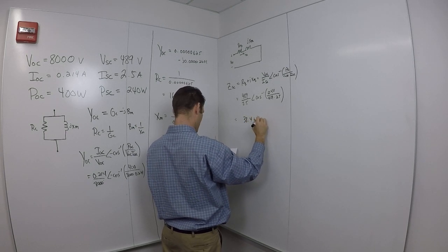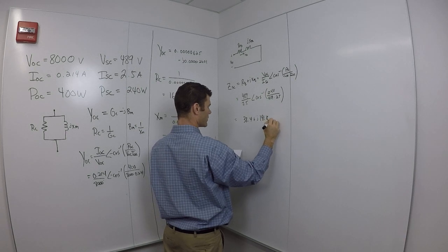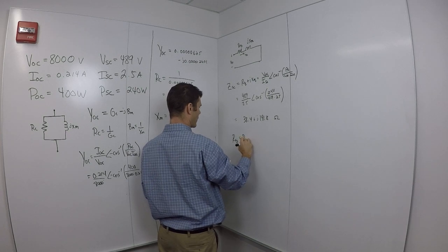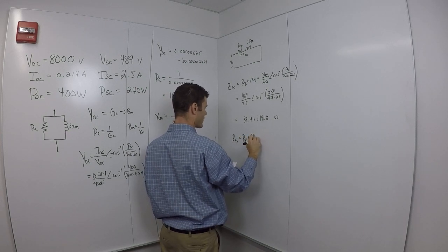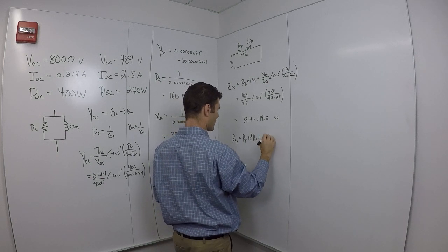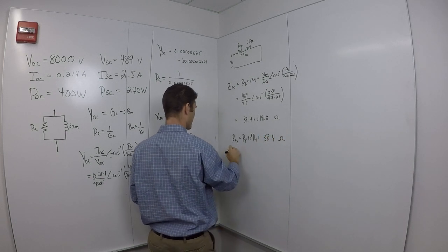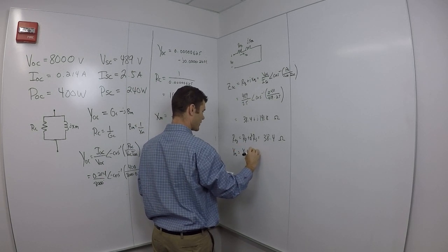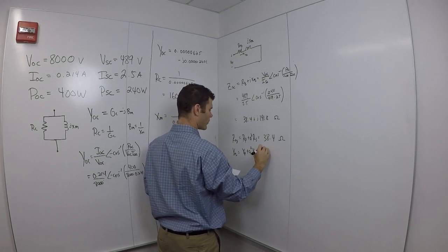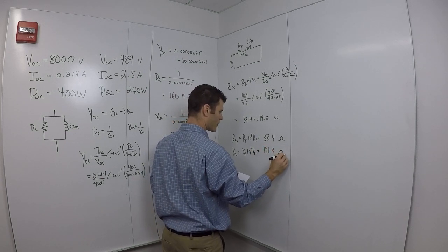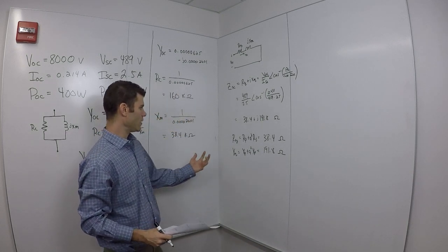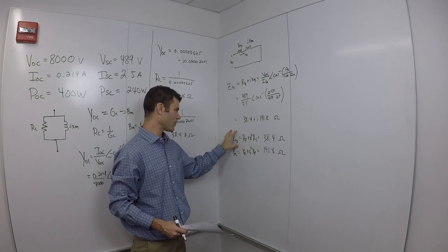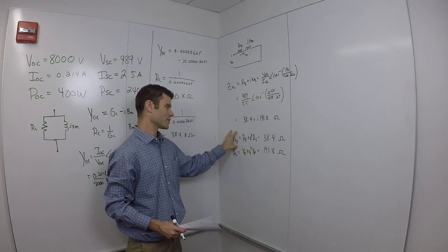38.4 plus J 191.8 ohms. So this means REQ, which is equal to the primary plus the turns ratio squared times the secondary resistance, is equal to 38.4 ohms. And then XEQ, which is equal to primary leakage plus the secondary leakage squared, is equal to 191.8 ohms reactive. Now, as you can see, we can't really find out what each one of these are, because we just have the combined value, which is the equivalent. That's good. That helps us for most of our analysis of transformers.